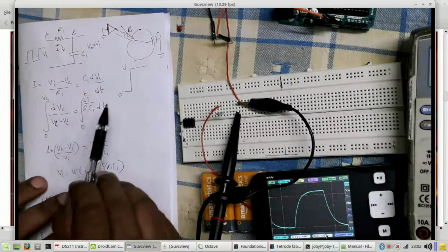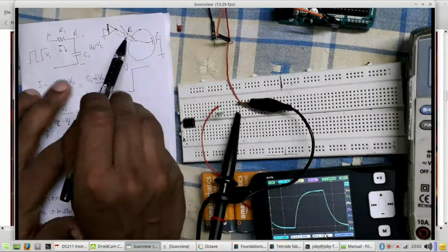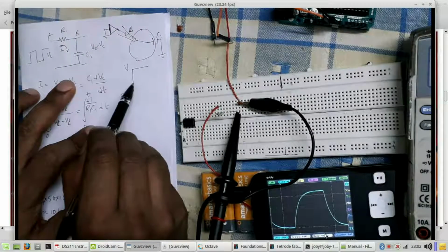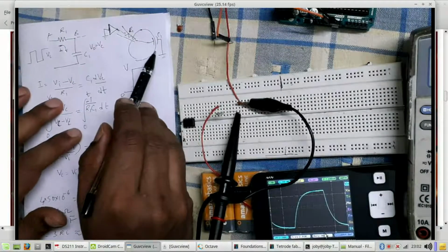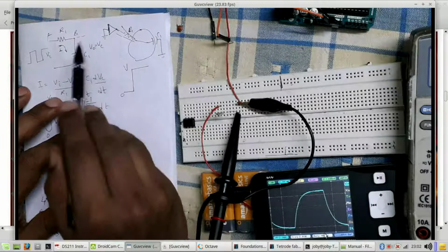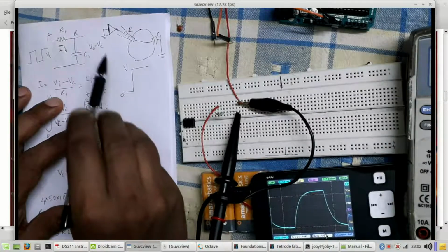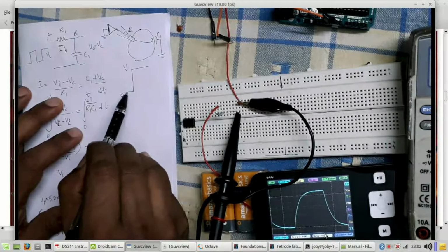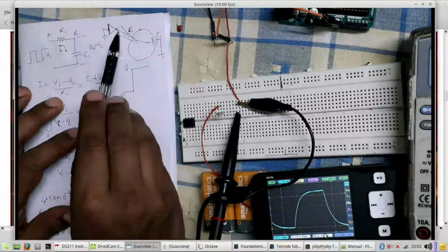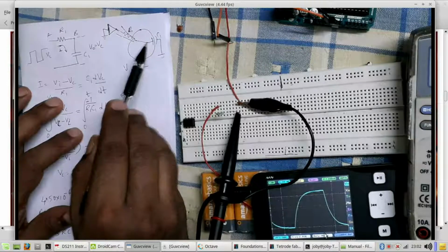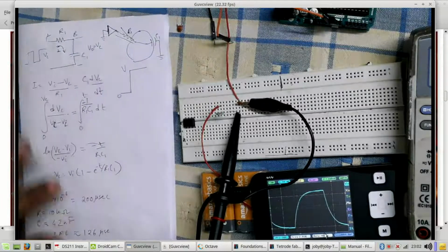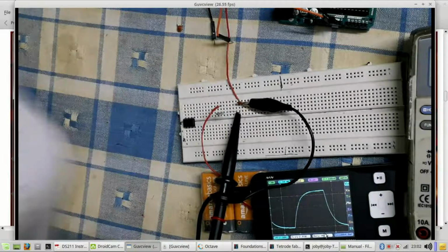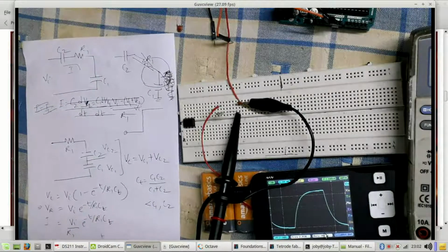So it is very clear that if you have a circuit like this, and if you want to make a voltage appear like this across the membrane, then the injected voltage corresponding to the current should be such that there is a voltage produced here which will produce this voltage at this point. And how is that possible, right? And that we do by what is known as capacitance compensation.